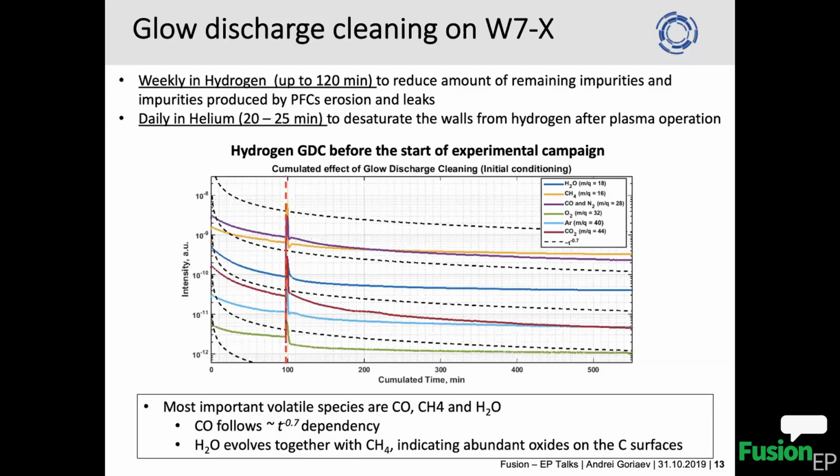I mean, in principle, there are calibration coefficients also for mass RGA, if I'm not mistaken, and then you can take some kind of pressure valves and do the calibration yourself by injecting some gas controllably by a mass flow controller, and then you can adjust those coefficients for yourself if you want to have that sort of empirical calibration to get that relation. This is the easiest way. So for instance, for main gases, you can calibrate it for sure for hydrogen, for helium, for deuterium, whatever gas you have.